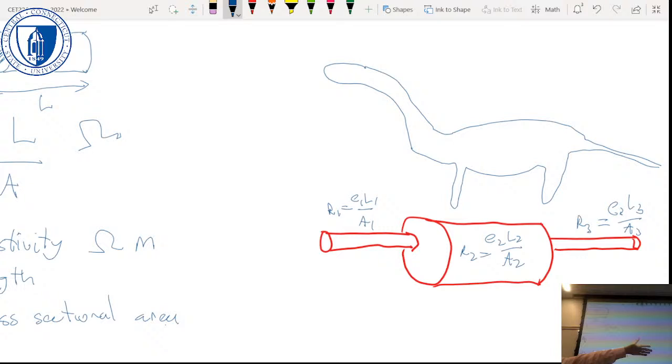They tend to use an alloy that mixes negative alpha material with positive alpha material, so the alloy has an alpha close to 0. Right? So they don't change resistance much as the temperature does. It's hard to get exactly 0.